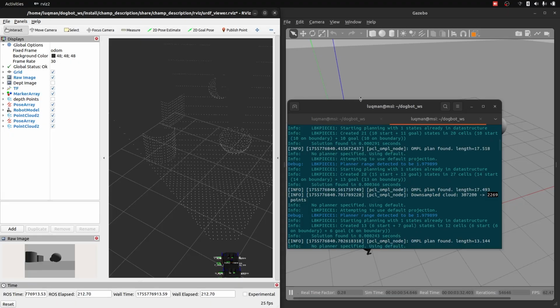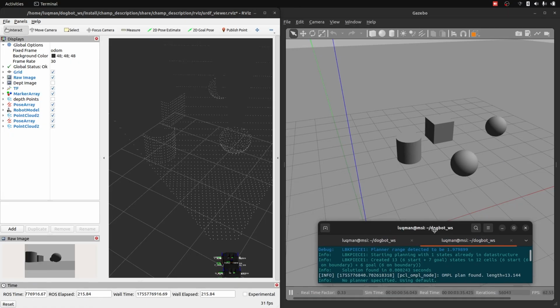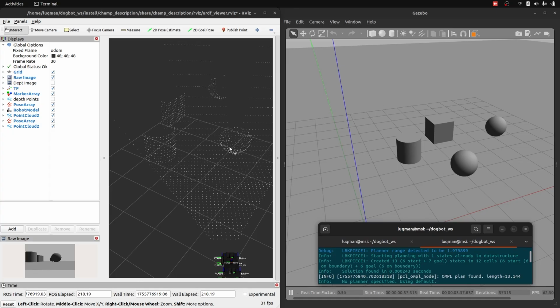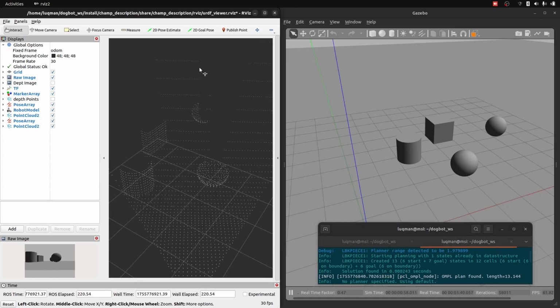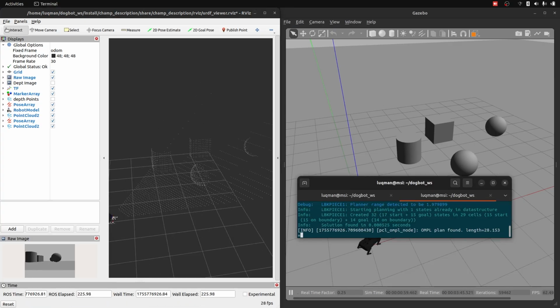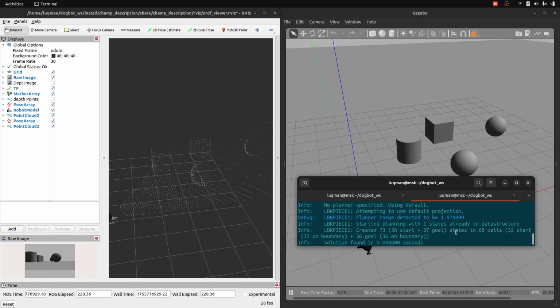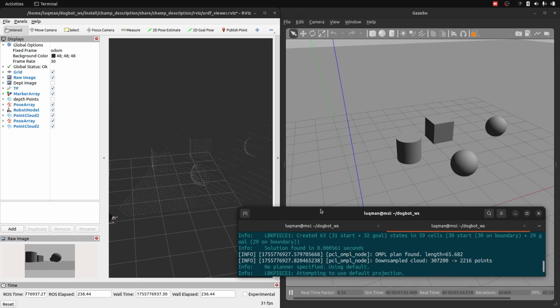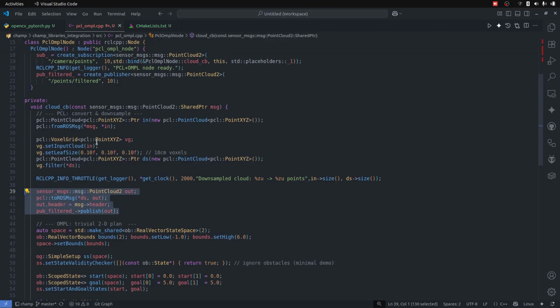But one thing to understand, you can see the structure is the same, and we can process the path planning in between it, and we are doing it. That's why the OMPL is logging things. Now what this is actually telling us about, if we scroll up to the point of reduction, for now I'm just running very small operations of downsampling the cloud, meaning reducing the number of points and taking an average, in this node that you can observe here. You can further reduce it. The size is going to reduce, the number of points are going to reduce.